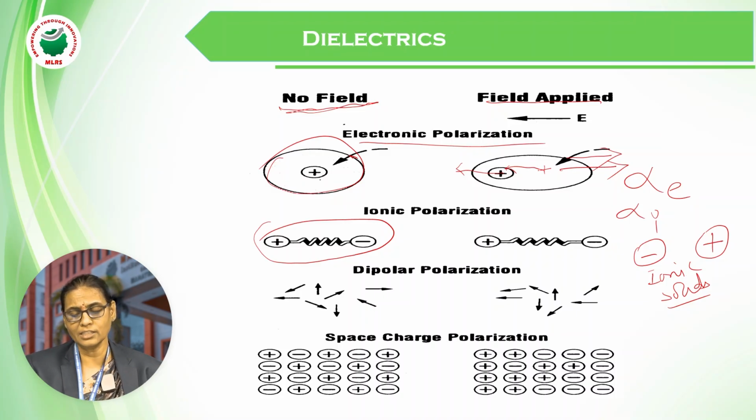First I give the definition, then I'll show you the figure. In general, the movement of electrons in any atom will be like this; this is how they randomly move. When you apply a field, the charge carriers align themselves along the direction of the applied field. See, this is the direction of the applied field. All the charge carriers try to align along this direction. That type of polarization is called dipolar polarization or orientation polarization, which is represented by alpha naught.